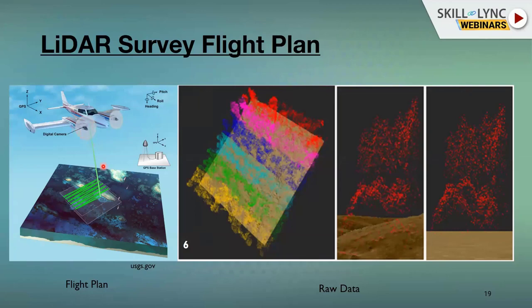As we know, the drone has no pilot, so the flight plan should be very precise. Based on that flight plan, the drone will fly the path and capture the data. In an aircraft or helicopter, obviously the pilot and co-pilot will be there, and if there are any issues on the trajectories, they can correct them manually. But in drone technologies, it is not like that. The data acquisition is 60-70% similar to airborne, but the rest of the things in the drone are fully autonomous.